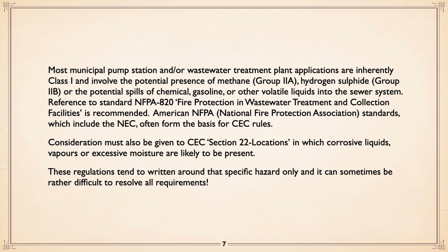Most municipal pump stations are inherently class 1 and involve the potential of group A and B gases, or potential spills of chemicals and whatever. That can happen. Ruptured gasoline tank and it gets into the sewer system.